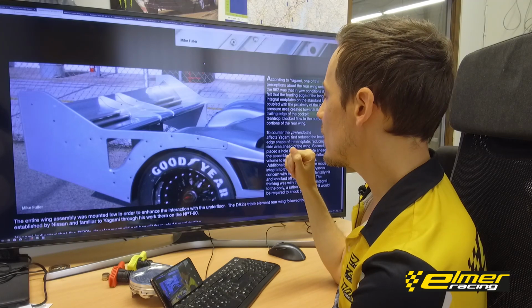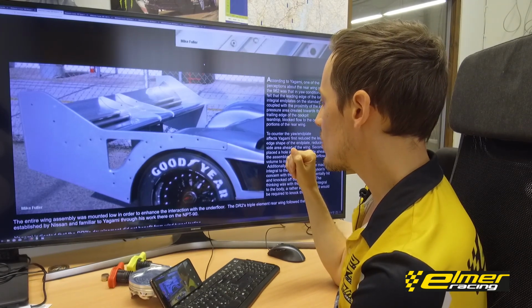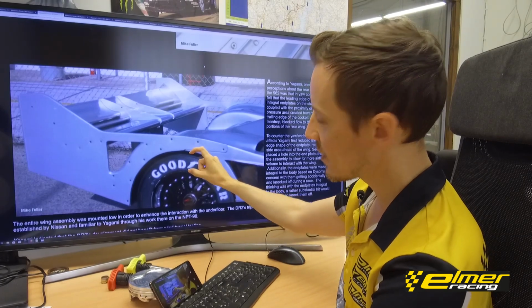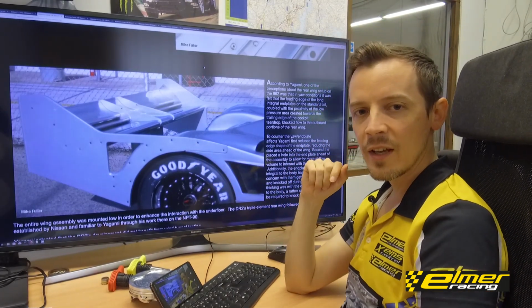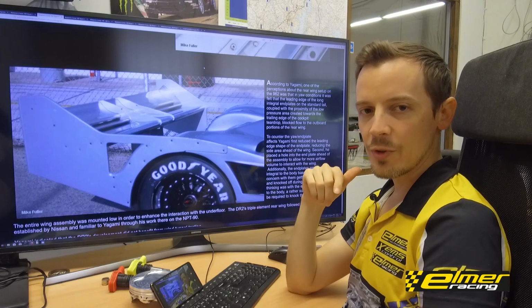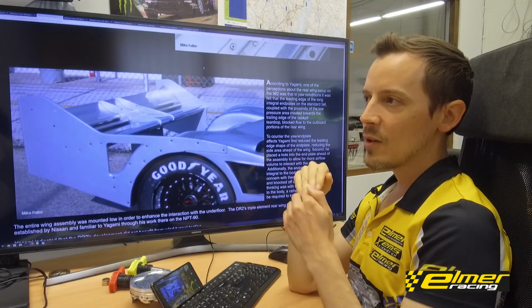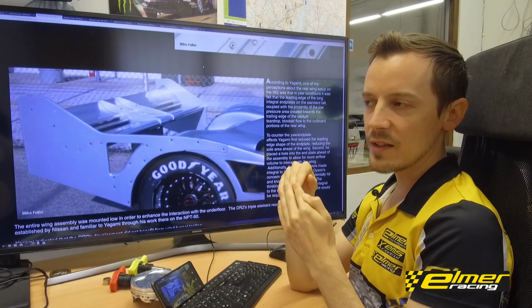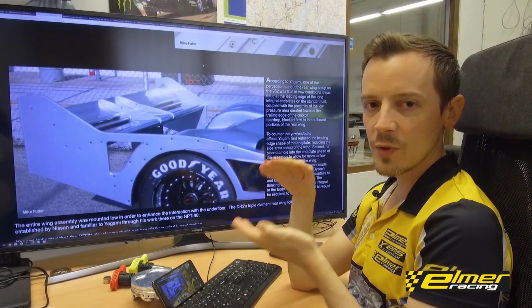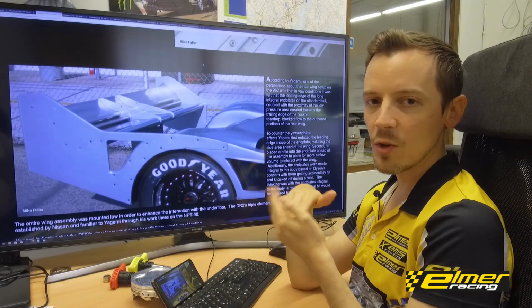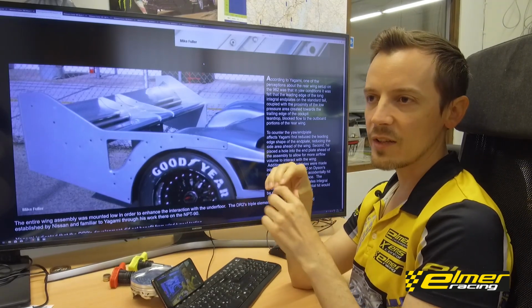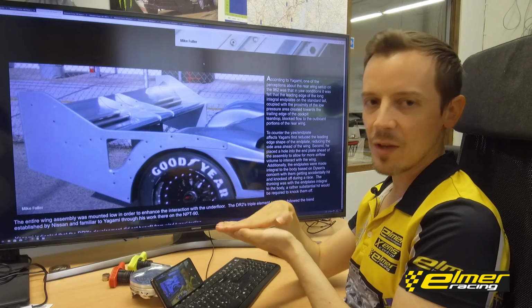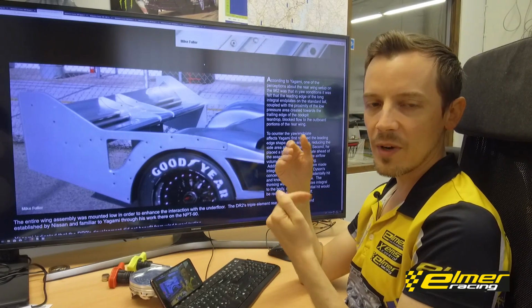Yeah, and this is maybe quite an interesting car. One of the other aspects to note here is the height of the sidewall of the tire. This is a really good indicator of how much downforce cars produce and how fast they are, because once you start getting up to 300 plus kilometers per hour, then on high downforce cars, the downforce levels will be so high that you have no possibility at all of running really low profile tires, because the tires will just be completely flattened basically by the amount of downforce.